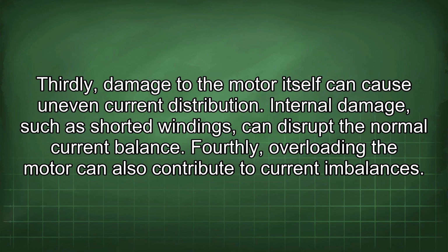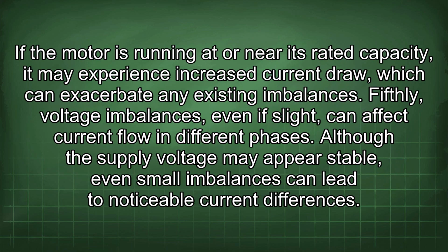Fourthly, overloading the motor can also contribute to current imbalances. If the motor is running at or near its rated capacity, it may experience increased current draw, which can exacerbate any existing imbalances. Fifthly, voltage imbalances, even if slight, can affect current flow in different phases. Although the supply voltage may appear stable, even small imbalances can lead to noticeable current differences.